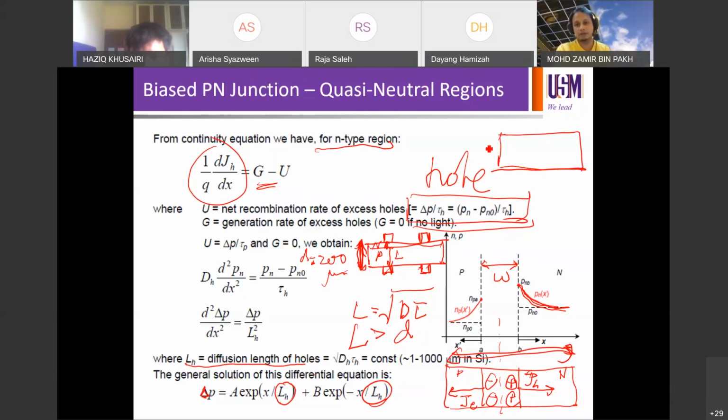Okay, say this is 200 micron, the whole thickness, p-type, 200 micron, twice of a hair thickness, more or less. So in the real device, in the actual world, you don't dope like half of the thickness. It's not 100 micron for N-type, 100 micron for P-type. That's not the case. Because that just cannot be done practically, because the process of doping the surface takes quite a long time using high temperature.